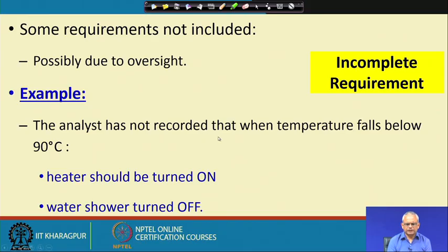We should have actually recorded that when the temperature is less than 90 degree, the heater should be turned on again and the water shower should be turned off to maintain the temperature between 90 and 100.